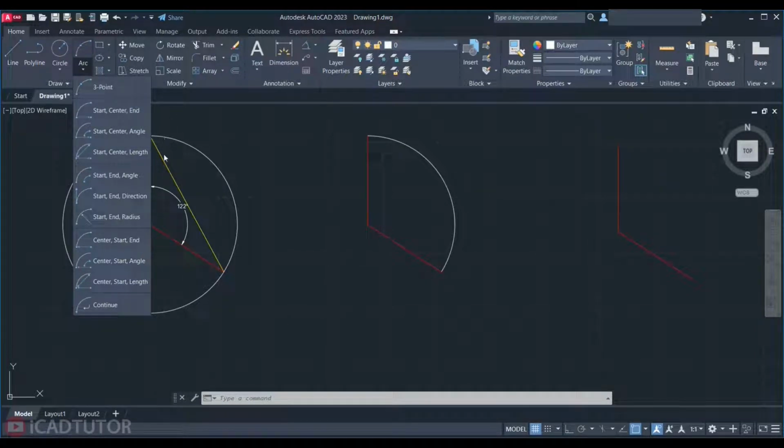I see that they are exactly the same but have one difference: in these 3 methods we must first specify the first point and then the center, and in these 3 methods, first we must specify the center and then the start point. Now if you don't care to start from the center or from the first point, join me to know how to draw an arc.